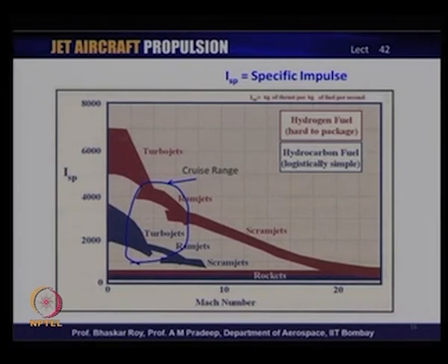The trouble with them is that the hydrogen fuel, the liquid hydrogen, is light, and as a result carrying a certain mass of fuel would require more volume and hence more space in the aircraft. Now, that is something which till today the aircraft designers are not ready to concede, that extra volume or extra space to the hydrogen fuel. And as and when that issue is resolved, it is probable that we will move from hydrocarbon fossil fuel to liquid hydrogen, which of course is indeed a better fuel by all considerations.